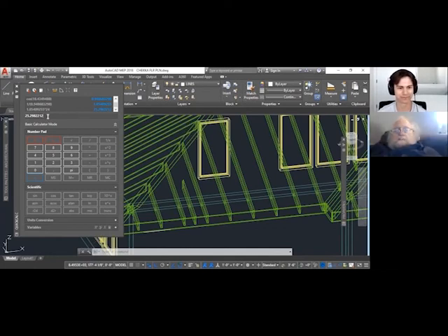So I can just simply take my calculator and run up a whole line of jacks and write them down. Each time I hit the equal sign, I'll get another length jack. And then I've got a whole set. Of course, at some point, they're going to exceed the length of the common rafter. And at that point, I know just when to stop.